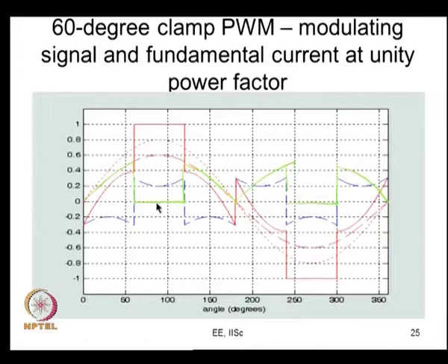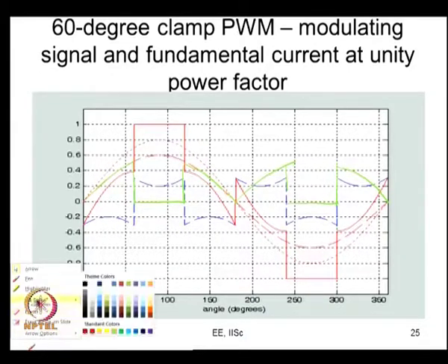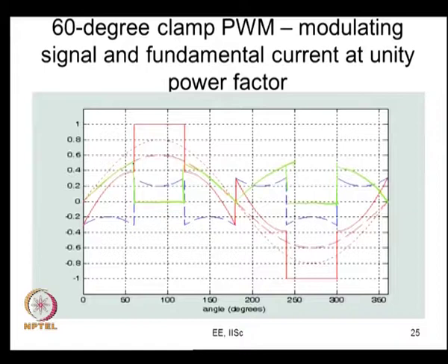Now, this is the local switching loss if I consider the carrier frequency to be the same as the conventional. If the carrier frequency is 1.5 times the conventional, this will get multiplied by 1.5. So, what is the number here? It is 0.6 sin 60, 0.6 into 0.86, something a little higher than 0.5.